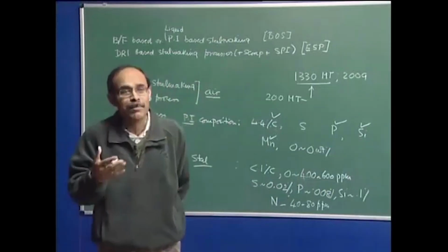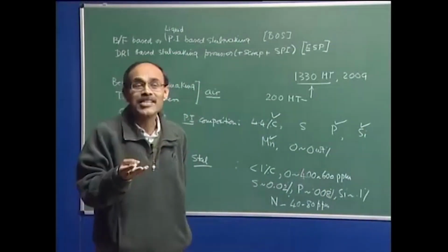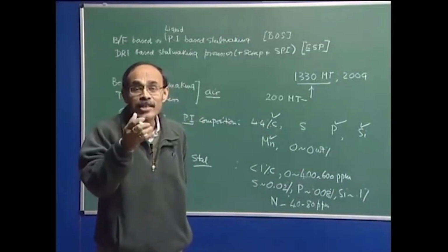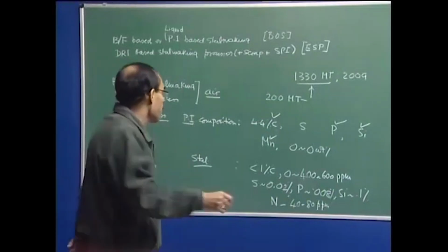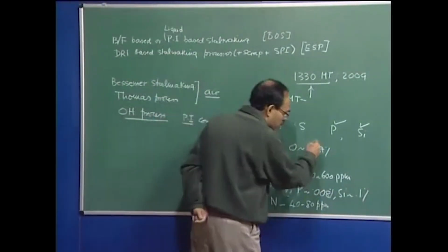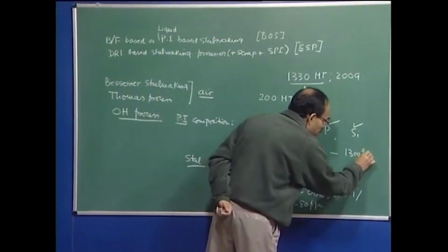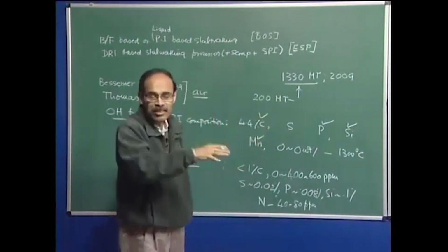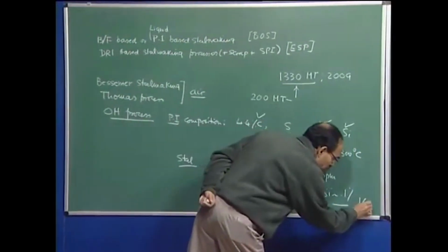Because in the steel making reactor also we have to supply heat for many jobs. For example, lime dissolution, slag formation, these will necessarily require heat. Where is the heat going to come from? The pig iron, at what kind of temperature is it tapped? It is taken out of the blast furnace at maybe about 1300 degrees centigrade. Again, this may vary, 1350 or so. On the other hand, we have steel making at 1600 degrees centigrade.